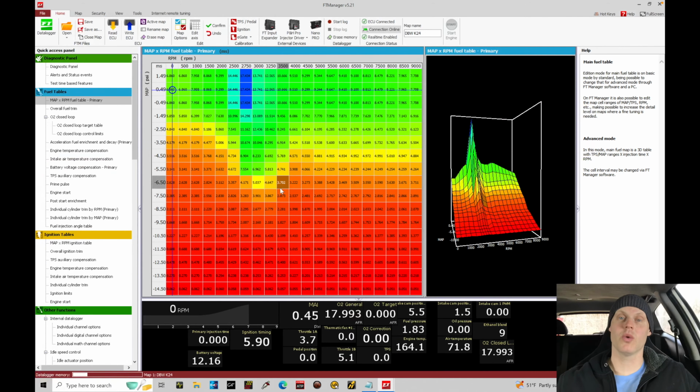In this training module, we're going to be taking a look at dialing in our full throttle once again, but we're going to be engaging VTEC and learning how to calibrate our fuel, spark, and variable cam control relative to our VTEC being engaged. We'll find that things change when VTEC is on. It's going to give us a completely different cam profile for the engine to operate on.